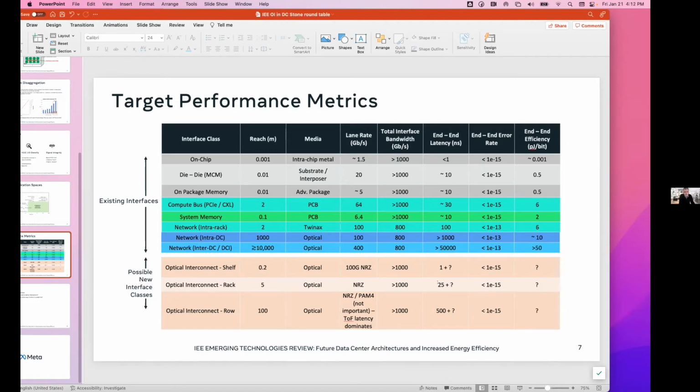Okay, got it. So Rob, I wonder if rather than reach, what matters might be margin. One solution being a lower margin than the other, at least if it is single mode fiber. So, link margin, link loss tolerance. Yeah, that's a good way of thinking about it. So it sounds like if what Ram's asking for is true, when he needs an optical switch, we might need more than 4 dB or 3 dB. Yeah, because the optical switch losses, the best ones are in the order of that range already before you've added any other connector loss.